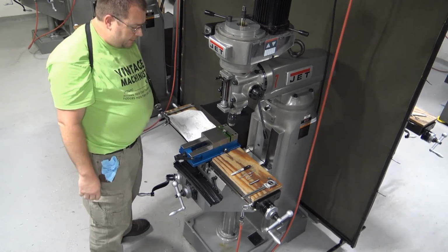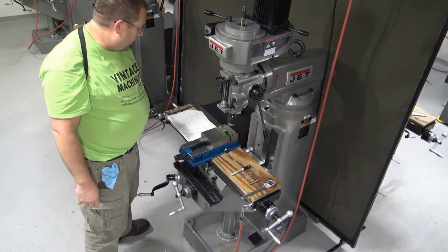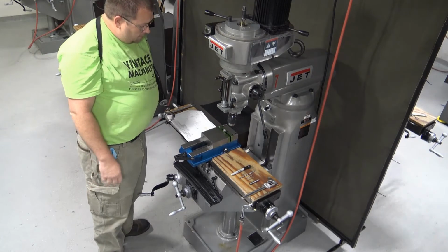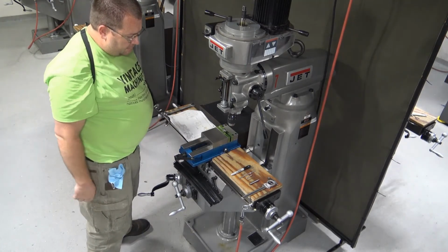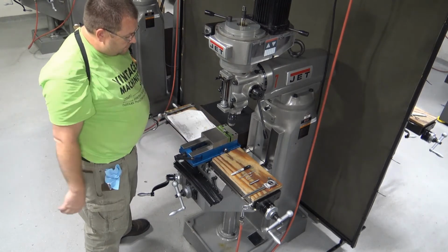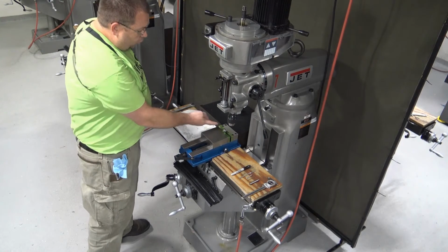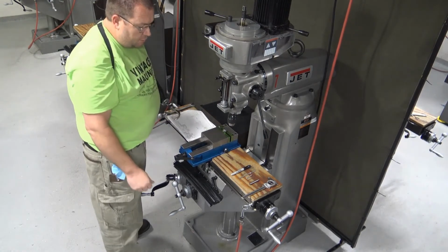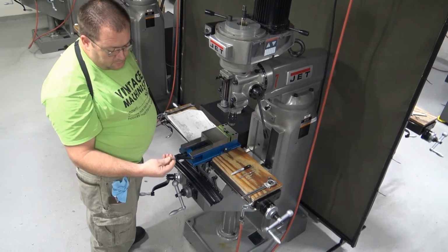Now we have a mechanism to get that out of there, but I prefer not to have to go through that process. So previous to that, we went ahead and indicated our vise end, so we're within our 2,000ths indicating of the fixed jaw. Remember, we only indicate the fixed jaw. So now we're ready to find the hole location.